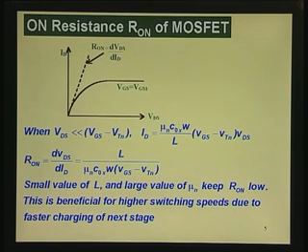Now, what we saw in that series, that resistance R which was coming at the input, which decides the cutoff frequency, is actually the on resistance of the previous device. So, now let me tell you what is on resistance, I have put this diagram. Here, this is the output characteristic of the MOSFET for one gate to source voltage. Okay.